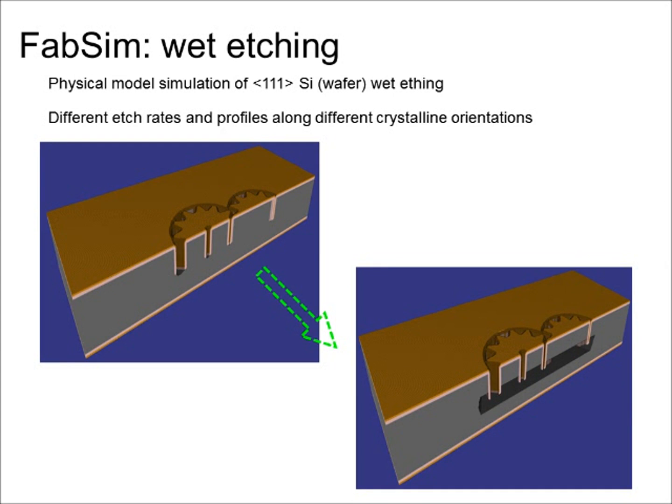And here is an example that shows wet etching. And instead of traditional methods where you would just have a geometric based method, here you can see the etch cavity under here. You're only going to get that accuracy with physical simulation. So for wet etching specifically, it uses a cellular automata method with kinetic Monte Carlo algorithm, the same method used within IntelliEtch.